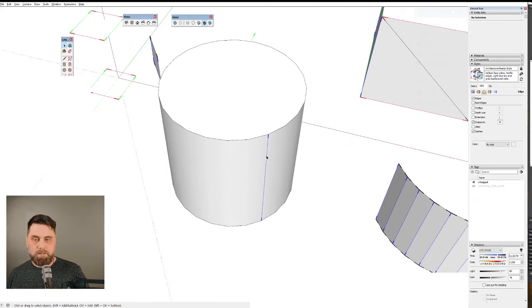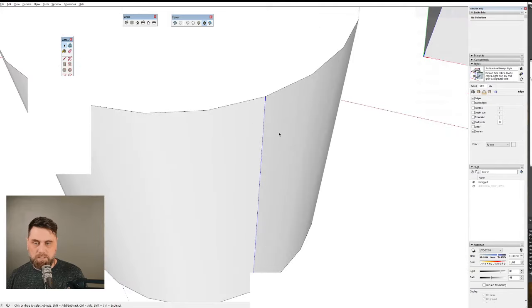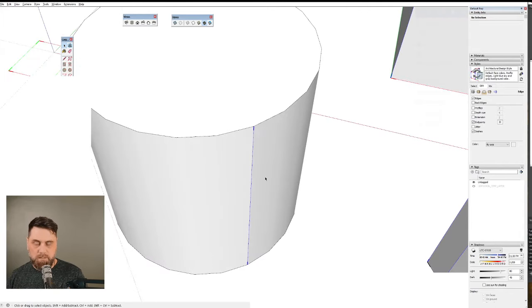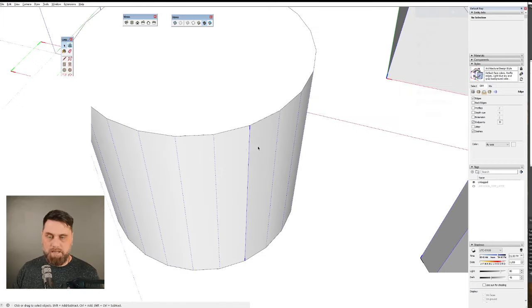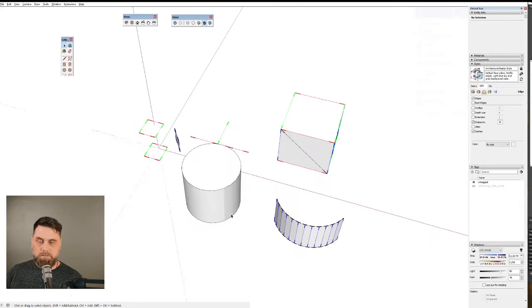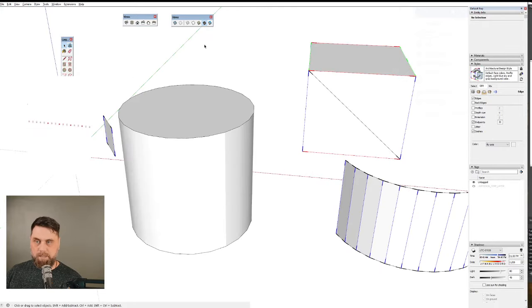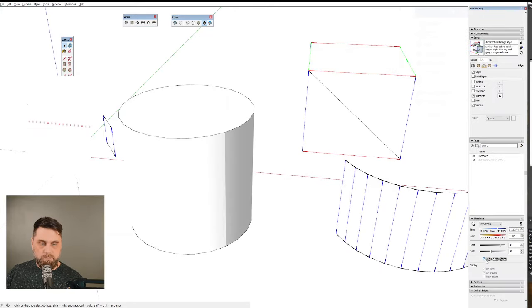But if we come up here, grab that edge again, and toggle smooth off, now you can see that it changed the shading in between those two sides. There are two small straight coplanar faces on either side of this edge. Now it's a little sharper in between because we turned off soft or smooth. I can make it soft and turn off smooth. And you can see, I don't know if you can pick that up there. Maybe I have to turn on, there we go.